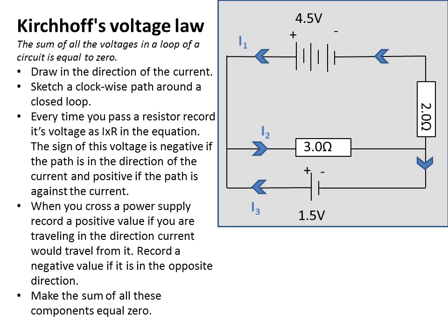And then I complete it by putting the arrows in for currents where they must be on the other parts of the circuit. Once I've done that, in order to calculate the total voltages around each loop, I need to determine a direction I'm going to travel around the loop. In this case, I decide I'm going to go clockwise. Okay, so I'm going to travel around the loop clockwise.